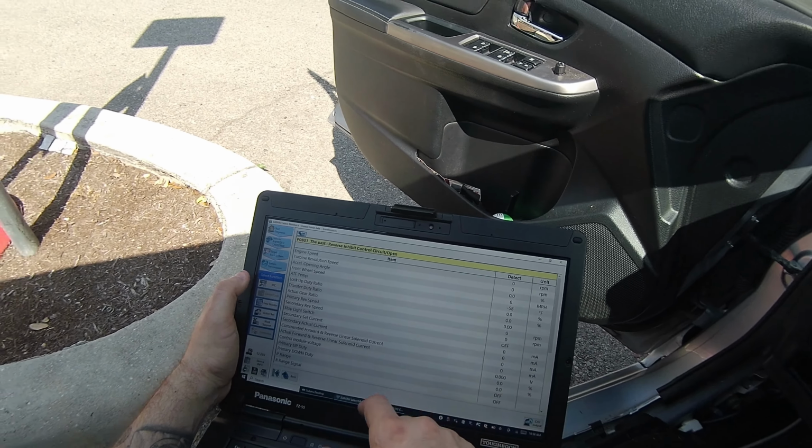With freeze frame, the computer will snapshot what has happened in the last second and the last 1.5 seconds. Each column after the detection is supposed to represent a half a second. Okay, that's 500 milliseconds. 500 milliseconds, 1 whole second, 1.5 seconds. That's generally all we need to see for detecting criterias of what's going on. So what I was looking for in all 3 of these columns here is I was watching to see if there was a dropout. Is there a dropout? And I didn't find any dropouts.